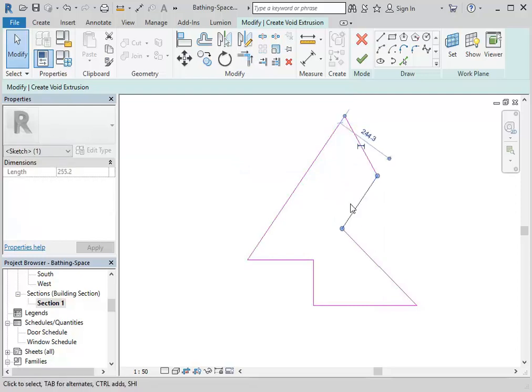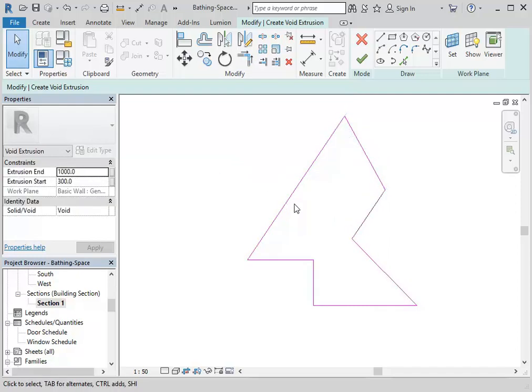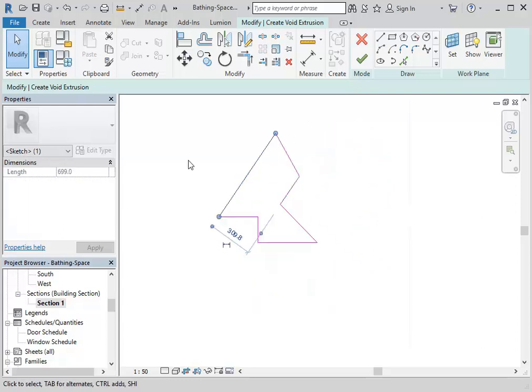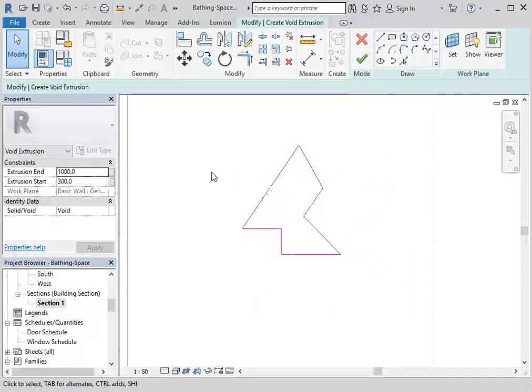So, yeah. Okay, but can you see that wouldn't be possible with an extrusion from the ground? It's an extrusion, obviously, but not from the ground. So then I'm going to make the extrusion start minus 150, and I'm going to make the extrusion end 150, just so I don't have to think about the direction, because when you go up to vertical, you often won't know which way's forward and which way's backwards.